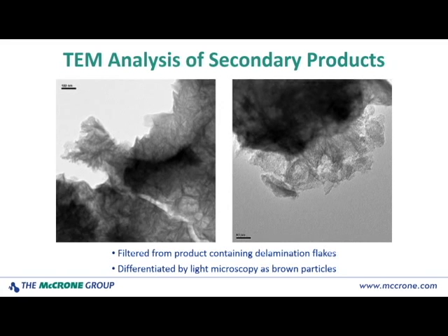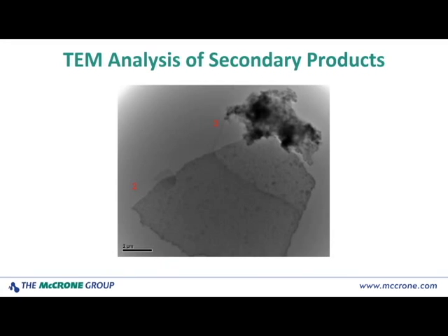And the cleanroom microscopist was able to selectively pick out those types of particles for transfer to a TEM grid. And you can see that it's got a texture and almost a layering or needle-like appearance to the microstructure readily evident in the TEM that tells you this is probably something other than glass delamination.